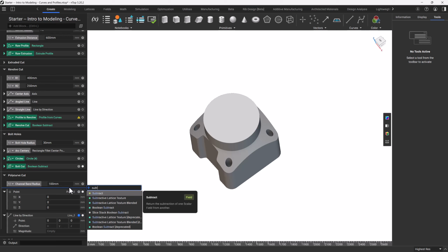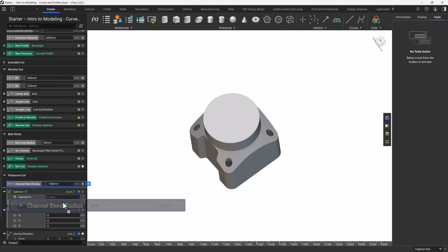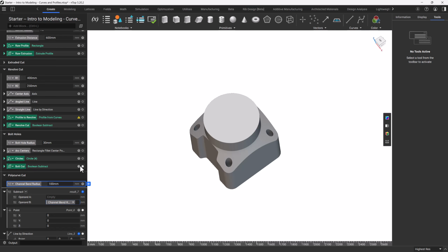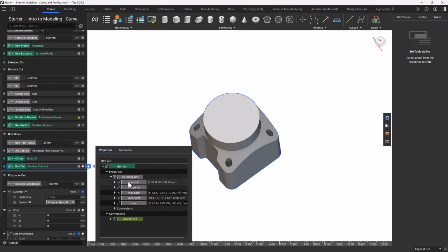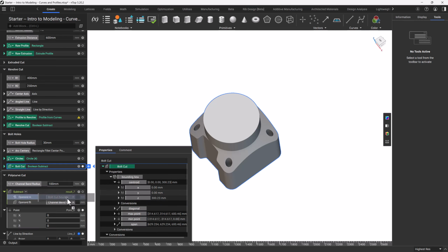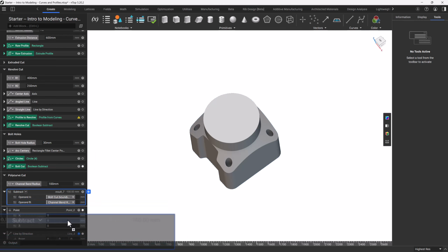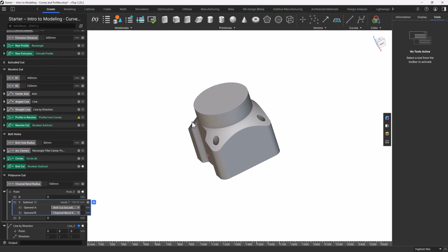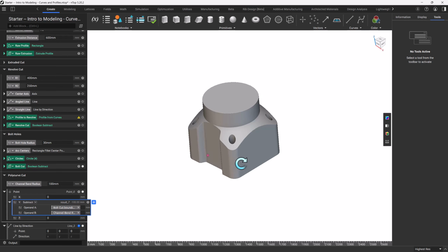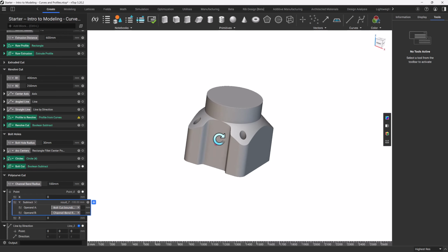So I can subtract 100 from the centroid of our above bounding box. And again, this will be from the Y value, which will then be negative 100, and this will be where our point is going to start in the Y. For the Z, or the height of where I want this line to be, I want it to be the extrusion distance divided by 2.5 down basically from the top, which is going to equal about 240 millimeters.